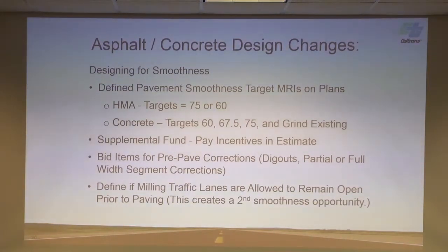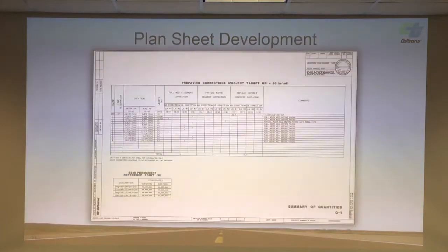And then the designers have the opportunity to determine whether or not the mill and fill will be allowed to remain open prior to paving. Typically they want to mill and fill in the same shift to reduce rocks and windshield breakage and all that type of stuff. But if we're allowed to leave it open for more than a single shift, it creates a second opportunity. And Pete will be getting into a little bit more later about opportunities and stuff.